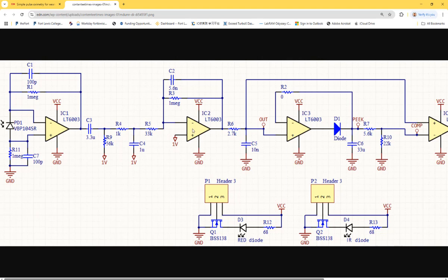Okay. And then another stage of low pass filter. Probably they observed some certain frequencies of noise. They want to get rid of it, so they added another low pass filter for some reason. And it's pretty much ready, so the signal is ready here, so that's why they put an output here. This is probably the original signal, shows the heartbeat.